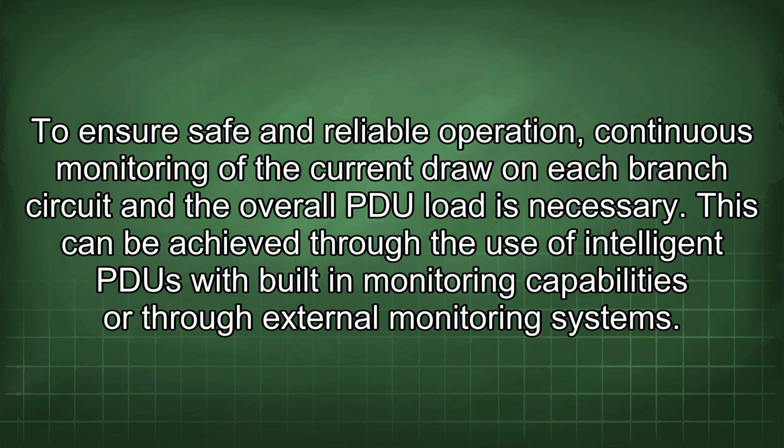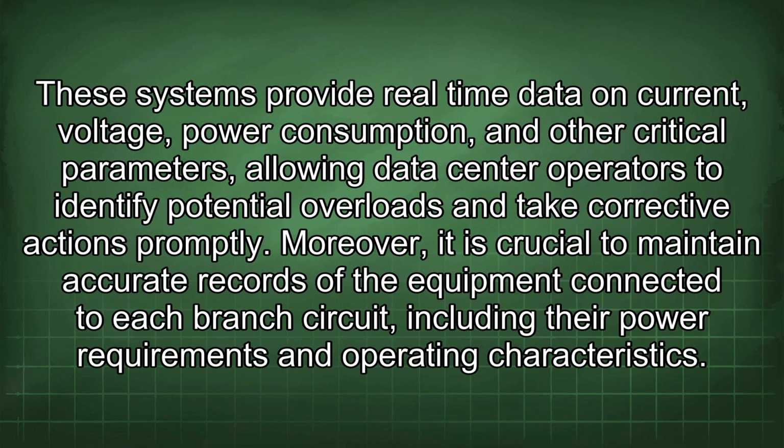To ensure safe and reliable operation, continuous monitoring of the current draw on each branch circuit and the overall PDU load is necessary. This can be achieved through the use of intelligent PDUs with built-in monitoring capabilities or through external monitoring systems. These systems provide real-time data on current, voltage, power consumption, and other critical parameters, allowing data center operators to identify potential overloads and take corrective actions promptly.